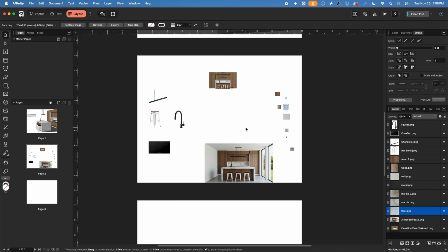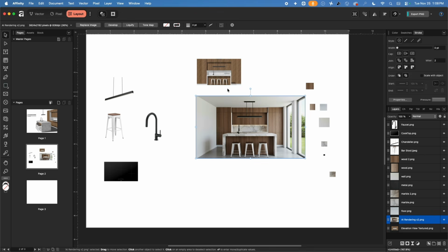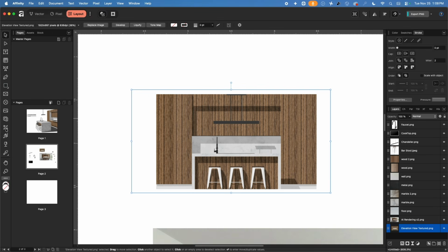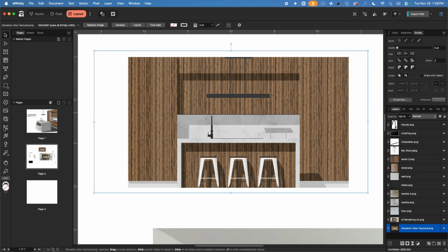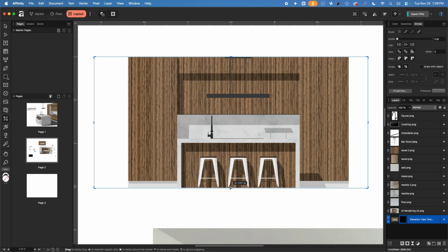So there's that. Very good. This is a box. This is a bigger frame. Here again, we can use this vector crop. So I turn vector crop on, bring this down to get close to the edge of the document. Very good.